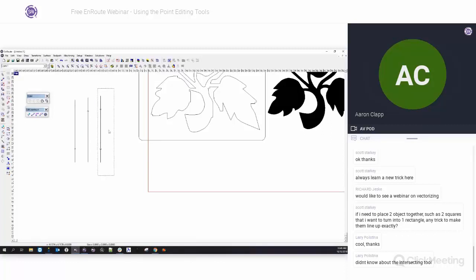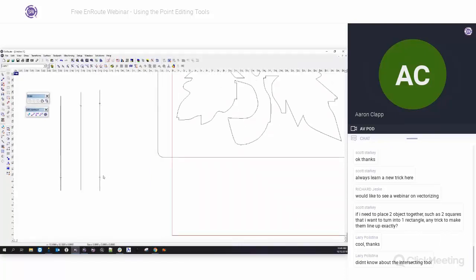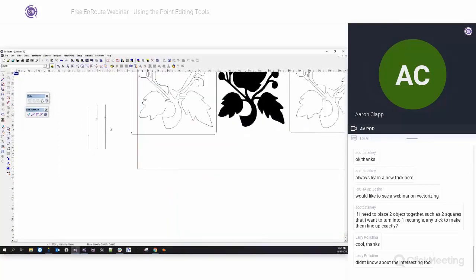But in this weird line, I actually have two. So if you ever see an open contour like this that has two chevrons pointing in opposite directions, you know 100% that there's something wrong with that line. And so if you click on one and delete it, now you're back to one. So that's another way of, especially if you're importing like a DXF file that's not merged together for you already, you might get a lot of those double chevrons for double contours and stuff like that. That would be the other thing to look for.